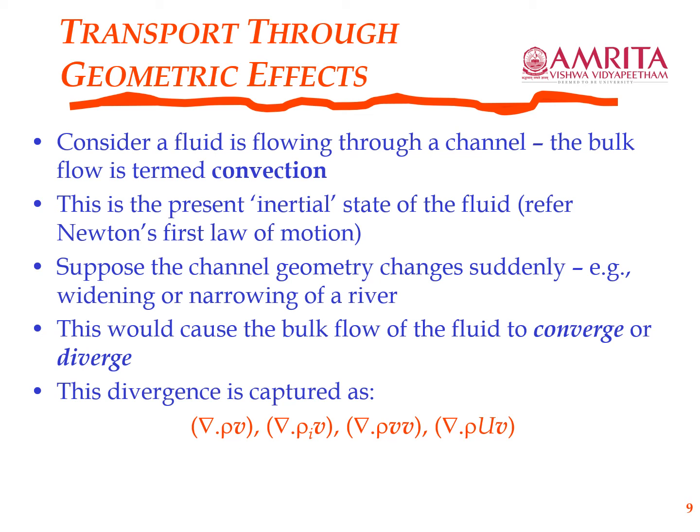So the net fluid that exits or enters this small infinitesimal volume is captured by this divergence, right? Actually, by this flux. If you want to capture the net amount of fluid that comes in, you should take the flux, which is, for example, the mass flux is rho v, and integrate over the entire surface area. That would be a double integral, and that will give you the flux.